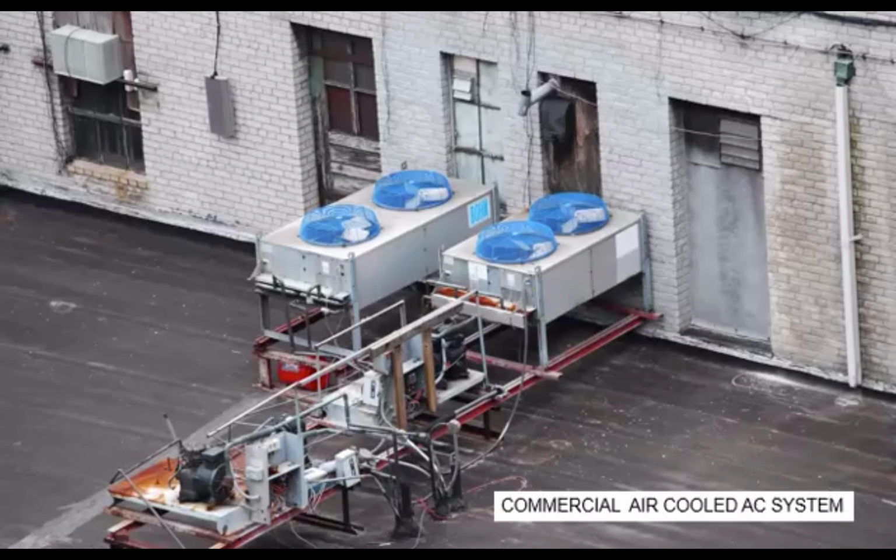And I had mentioned that this is critical because generally we also have a lot of HVAC considerations on the roof of a building, and basically deciding what kind of HVAC system you use will determine a lot. How much ductwork you need, the locations and reinforcements on the roof that you need to hold equipment, and then the number of lines that you need getting to and from each floor, and how that takes things out, whether it be water or air from the system that performs the cooling.